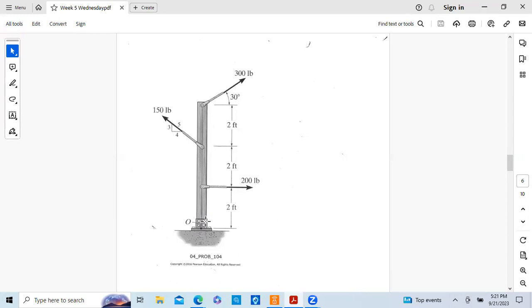And when we simplify this force system, that allows the engineer to design this support. And basically what that would mean, first of all, how many bolts do you need? And they've got 4 right here. So what type of bolt? And then more importantly, in terms of design, what is the size of the bolt? What's the diameter of the bolt?